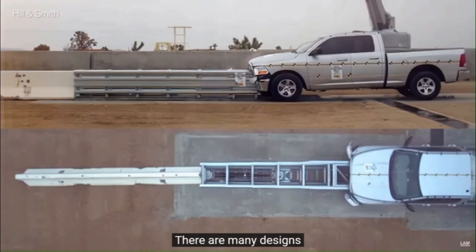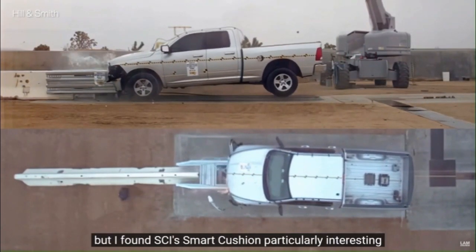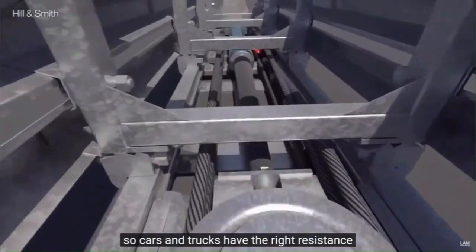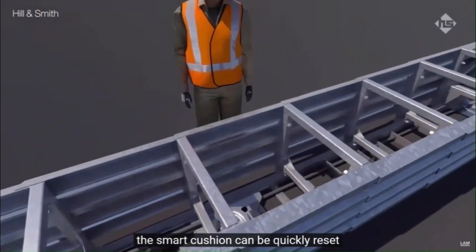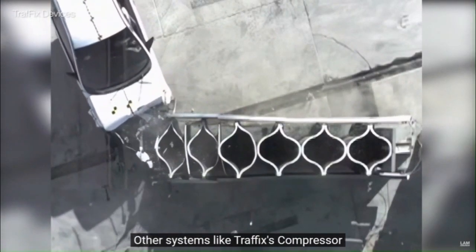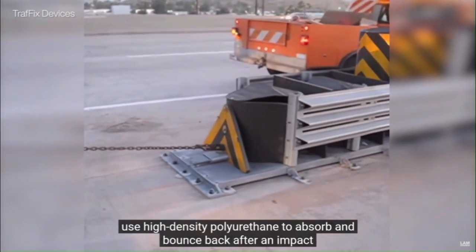There are many designs, but I found SCI's Smart Cushion particularly interesting. What's neat is the gas cylinder inside adjusts the stopping force based on weight and speed, so cars and trucks have the right resistance. After an impact, the Smart Cushion can be quickly reset by pulling it out and replacing a few bolts. Other systems, like Traffic's compressor, use high-density polyurethane to absorb and bounce back after an impact.